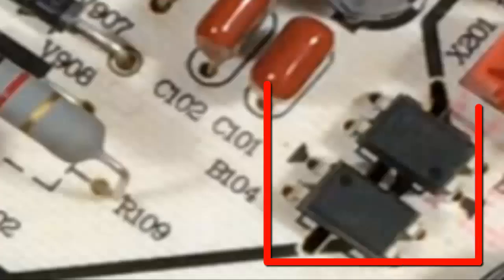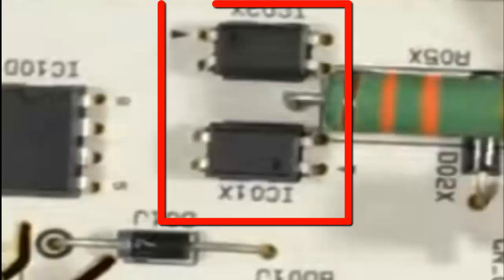2. Optocouplers can be found in the communication circuit between the internal and external units of the air conditioner. In split air conditioning systems, with indoor and outdoor units, optocouplers can be used to transmit signals between these two units without a direct electrical connection. For example, the electronic board of the indoor unit could use an optocoupler to communicate with the outdoor unit.